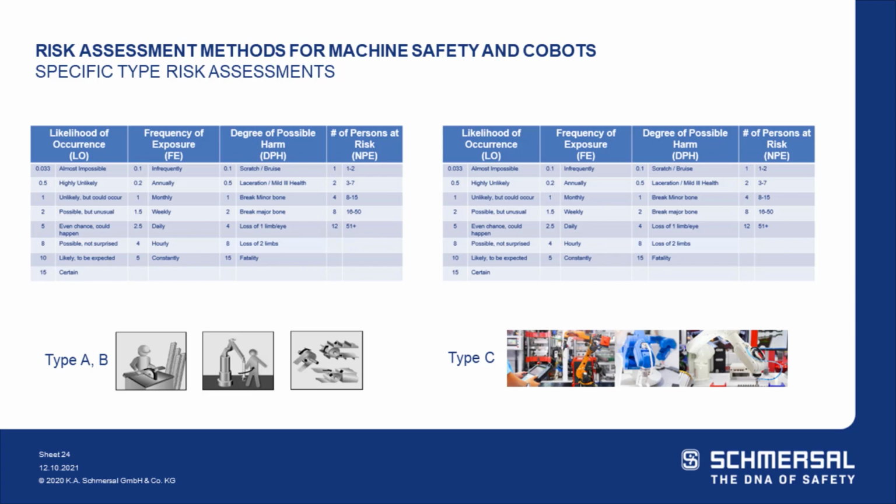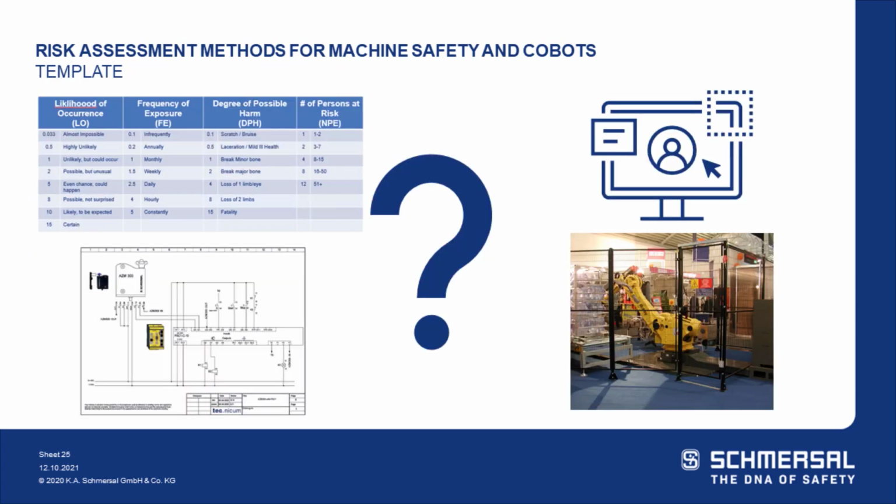So these questions from all the Type C standards, we want to put them into sections in your risk assessment. And if they do not apply, let's say you're reviewing a cell that doesn't have a cobot, then that section for cobots is not applicable, right? And that's okay. Therefore, you have a standard risk assessment you're doing everywhere, keeping it standard for all the types of machines in your operation. And if you add a cobot later, you can reopen that risk assessment and answer the questions for a cobot or a robot or anything with a Type C.